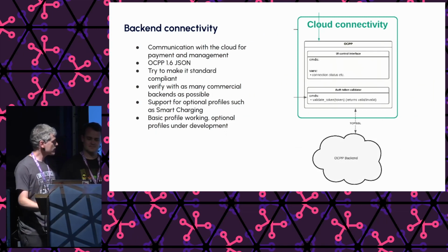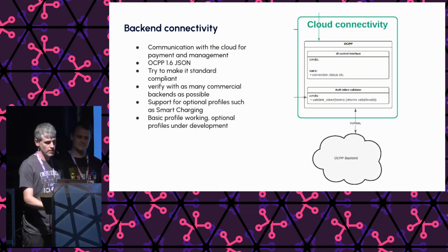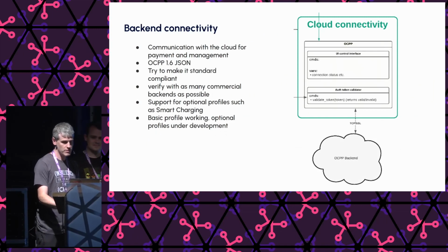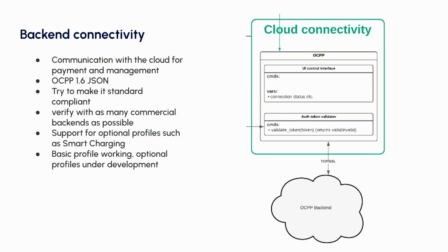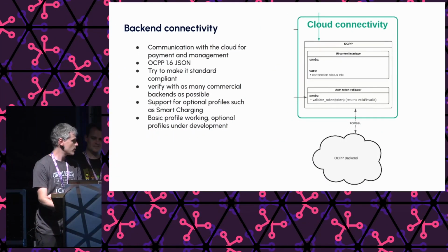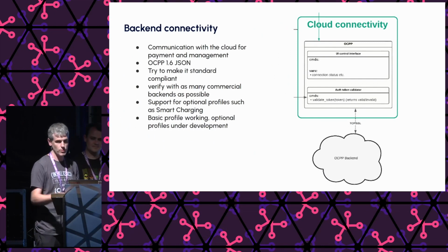Looking at the other side, not so much to the car, but to the cloud for payment and so on, we provide an OCPP 1.6 JSON implementation. We took a lot of work to actually make it standard compliant and not just our dialect of it. We verified this with as many commercial backends as possible, and also with the official protocol testing tool from the Open Charge Alliance, who supports the standard.